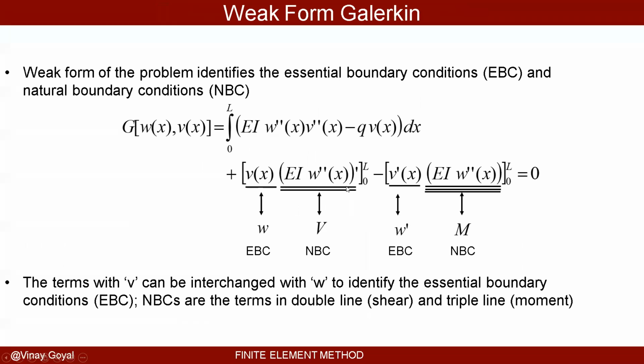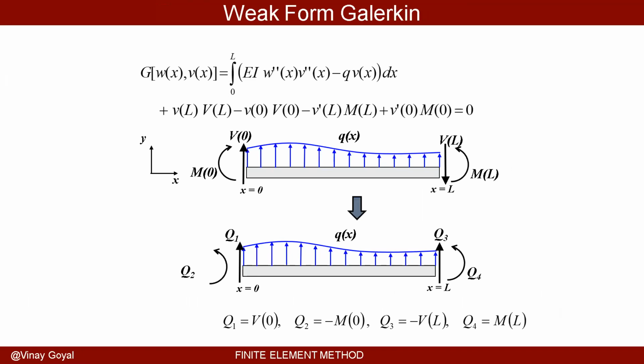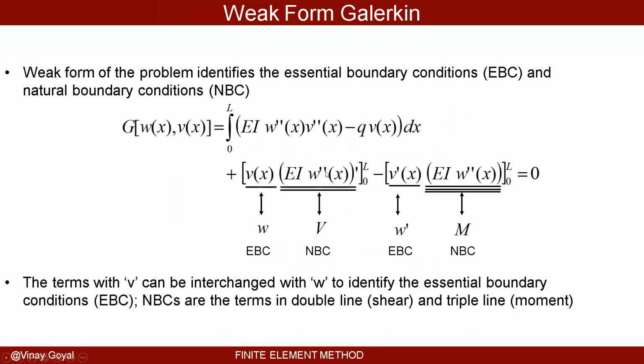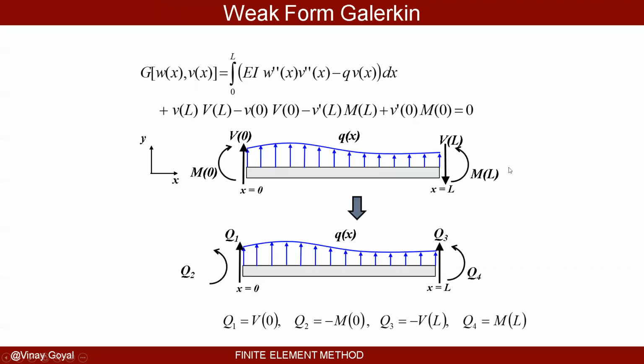And that's beautiful. We connected the reality of the problem to mathematics, because I could have given you this governing equation in vacuum and asked you to solve it. But it's really cool how, when you derive the weak form, you actually get quantities that have physical meaning. And that's quite exciting. So we already discussed this, but it's worth discussing. I can expand this term. So this shear here can be valued at 0 and L. This moment can be valued at 0 and L. When you expand that, you get this expression here.